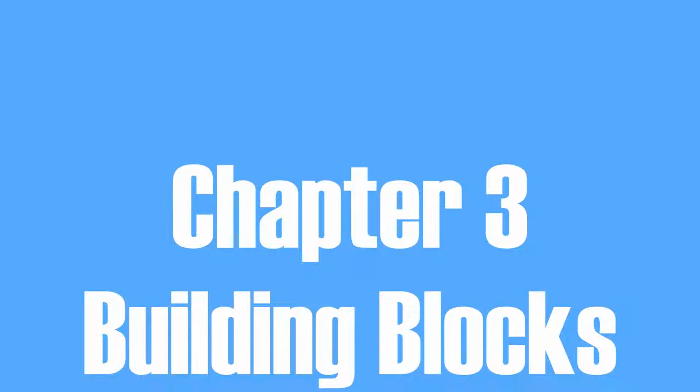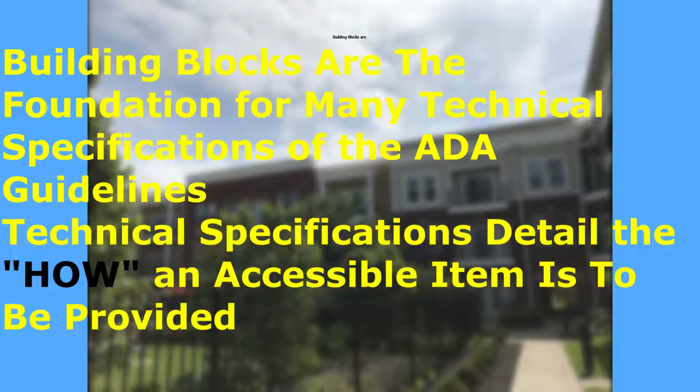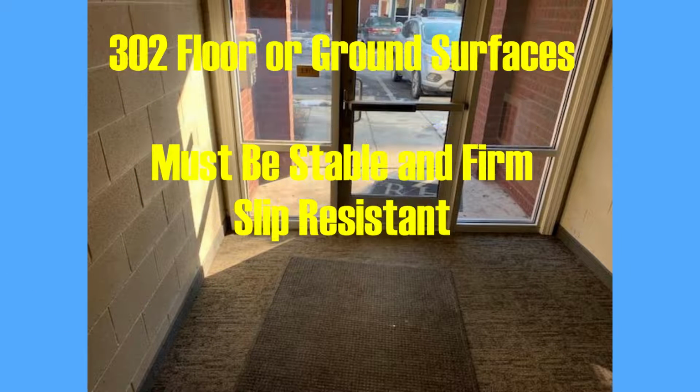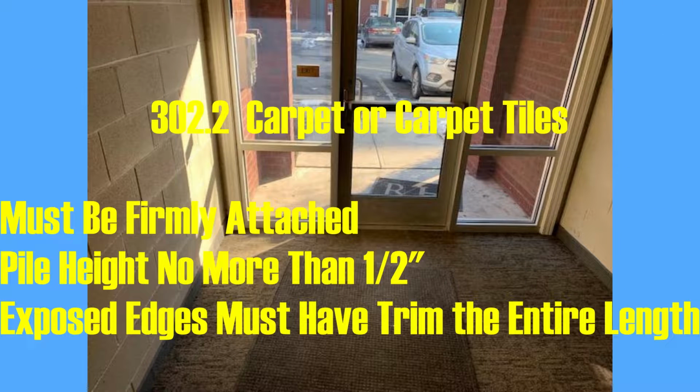Chapter 3 lays out the building blocks. Building blocks are the foundation for many technical specifications of the ADA guidelines. Technical specifications detail the how an accessible item is to be provided. Section 302, floor or ground surfaces must be stable, firm, and slip resistant. Section 302.2 indicates that carpet and carpet tiles must be firmly attached with a pile no greater than a half an inch, and exposed edges must have trim the entire length of the exposed edge.